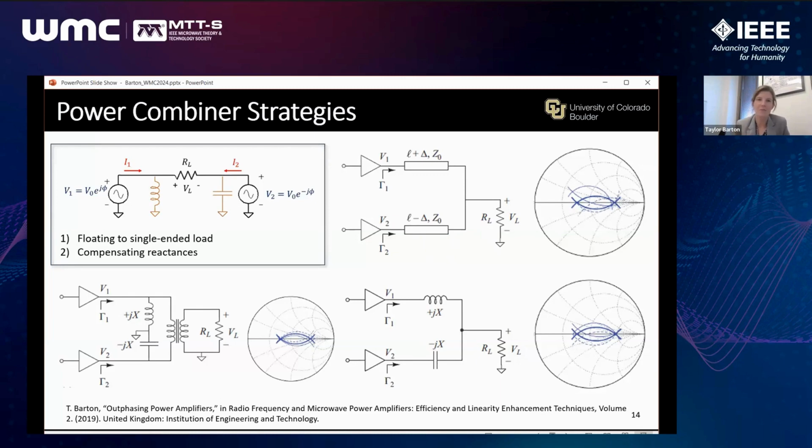Like plus or minus 20% accuracy on that inductor and capacitor, and especially with the inductor, you can run into self-resonance issues. So we did a little study and compared these two techniques on the right. The LC series works best in terms of loss if the values are correct, but was more sensitive to tolerance issues compared to the lines.